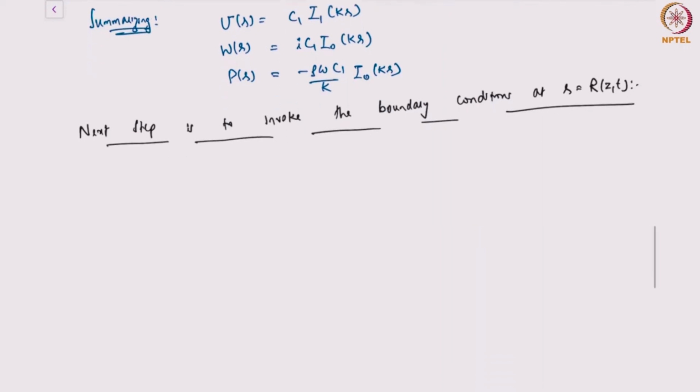What are the boundary conditions? Let's look at the first one. So I have an interface like this. I'm only going to draw one side of the interface. I have a bulge. So if I'm at any arbitrary location where the radius is R, the first condition that I have is called the kinematic condition.